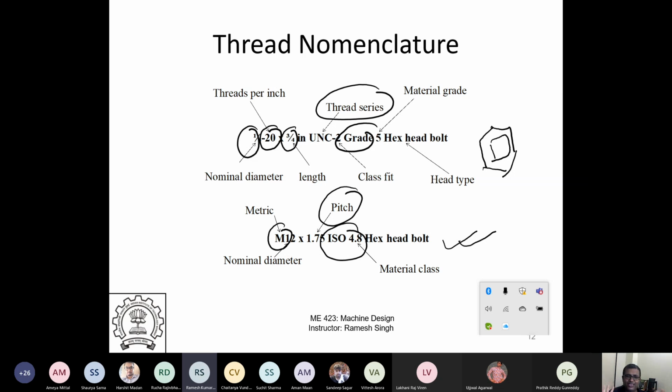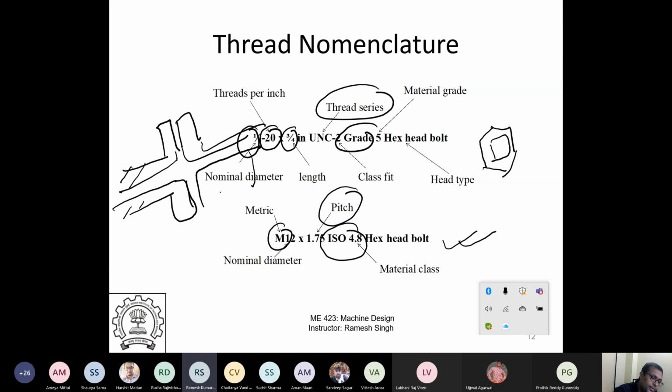Everybody knows what a flange is, right? Machine design course, actually flange is also a part of that. I may not cover those flanges, but you know, when we join pipes, we'll have a flange to join two pipes, something like this. Can you visualize? This is the thickness of the pipe, and this is a flange. There will be another flange like this, and there would be these studs, and there would be nuts on both sides. So studs will have no heads. You'll tighten with nuts on both sides, and the flange will get tightened. There will be a gasket in between to seal it properly.